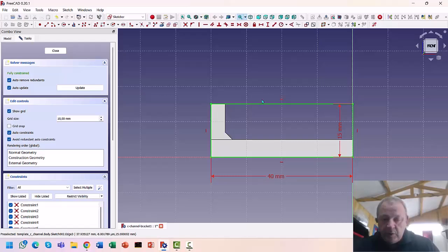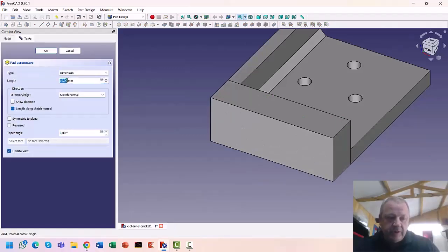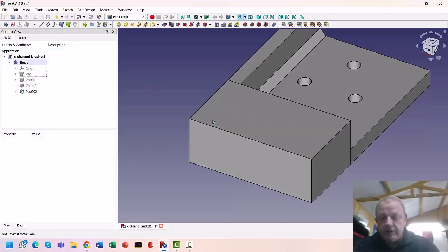So we are going to create a rectangle from this thing that is expanded 22 millimeters to the side. So we're going to set it to 22, and we say okay, there we go. So it's 22, it shows there. Great, fine. That's what we wanted for this one.